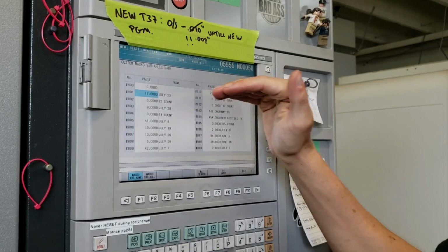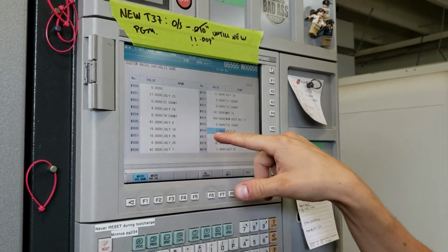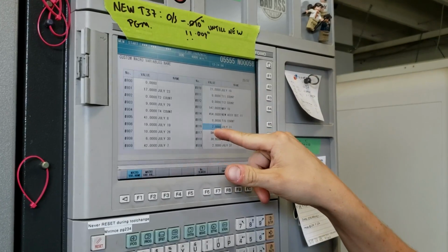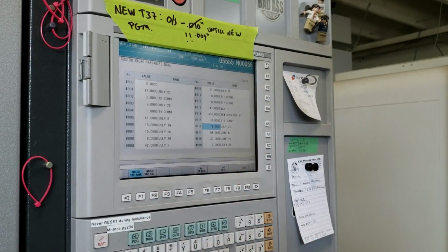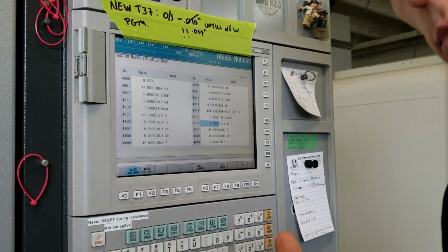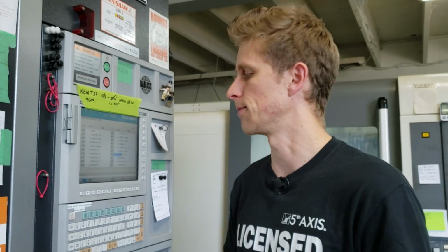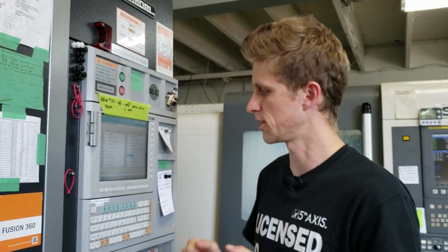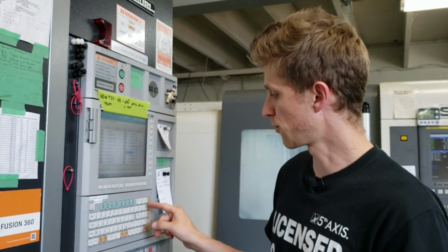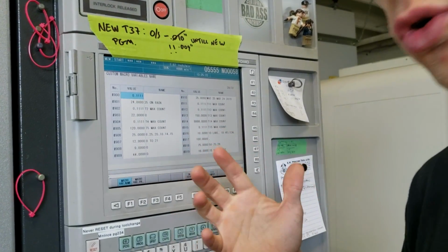So for every tool, we have it done. Tool 16, I know, is our 1/4 inch rougher. It's done 2 pallets. It was replaced yesterday, so last night's 2 pallets. After every single pallet, when the tool gets used, I'll show you a little bit later, the macro counter goes +1. So if it's using tool 16, it goes 816 +1, because you want the current value plus 1 more digit. And then for the 900 series, the numbers that I'm putting in here are just historical.